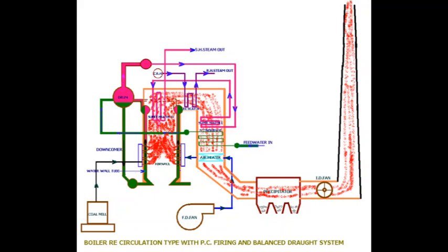Gradually the forced draft system, the FD fan system, was also incorporated, with the primary air supply system. As well, to evacuate the gaseous products of combustion, the ID fan, the induced draft fan, was introduced, so that it can take away the generated flue gas.